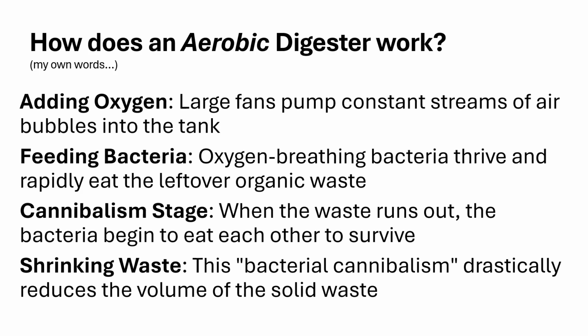We have something called a food to microbe ratio. That's an M. Not a great one, but it's an M. So what we do is we calculate the BOD, and that gives us the food portion of this ratio. And we're going to calculate something called the MLSS, mixed liquor suspended solids, a little bit later. Actually, you know what?